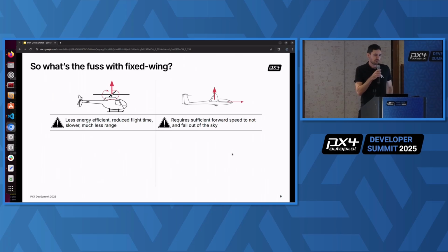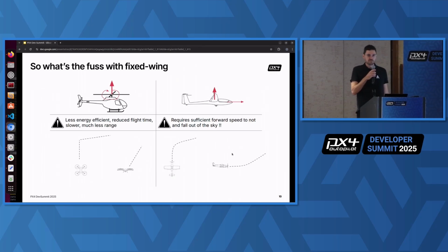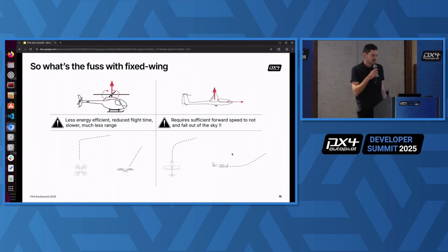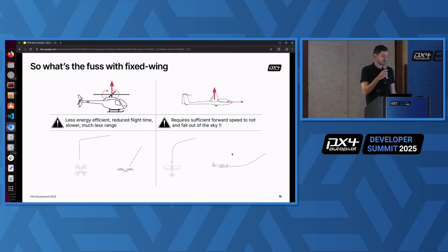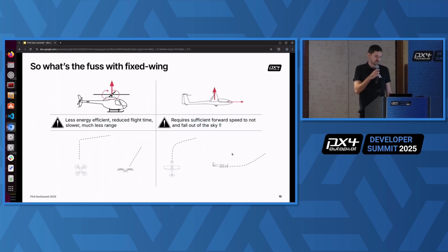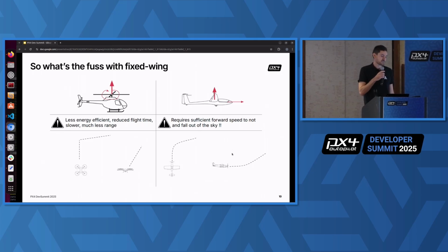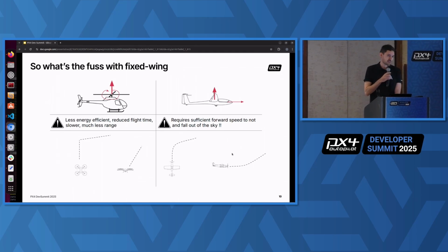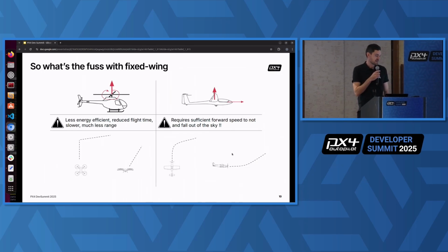So fixed wings move the whole body through the air, and through that generate the lift to keep airborne. What that means is, yeah, multicopters can fly any arbitrary envelope. They can stop in air, rotate, fly somewhere else, or fly any kind of steep flight path angle upwards and downwards, while fixed wings are really limited there. They always have to keep moving forward, or otherwise they fall down. And that has to be taken into consideration for the controllers and massively limits the possible flight paths.